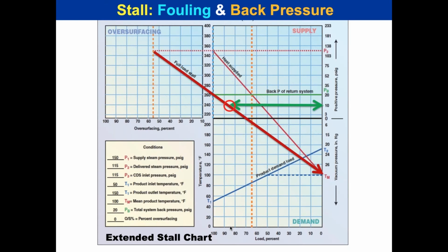Now, as a heat exchanger gets fouled, the effective surface area moves from 55% over towards 100% scale, like I'm doing here with this arrow. When that happens, from Q = UA delta T, since the effective area has gone down, the delta T has to go up, so the steam pressure rises. And there it goes.